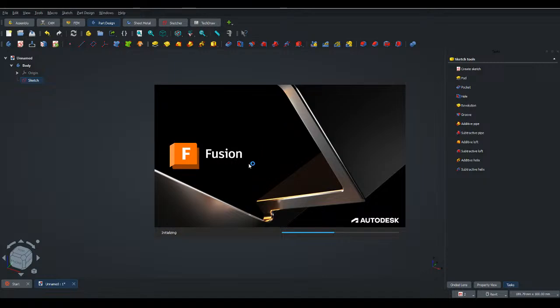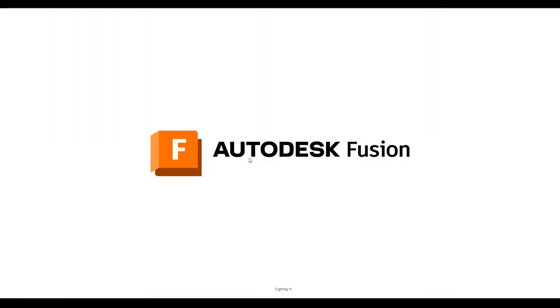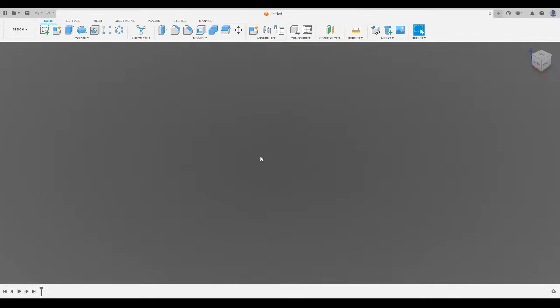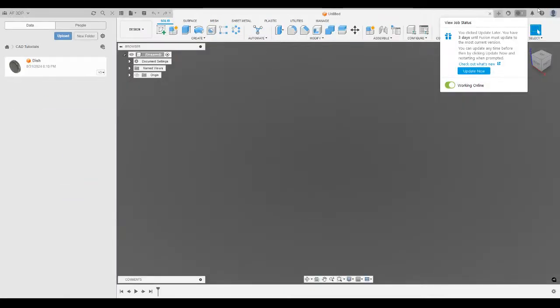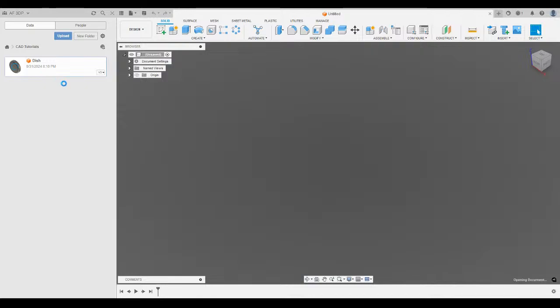I was trying to be the ADHD multitasker that I am sometimes, and I was looking, and there seems to be a way for me to actually do text in Ondsel, and it has something to do with taking a shape and putting it into the draft workbench, and the term that is being used is shape from text. But I will say that I have not been able to activate it. It was not working for me.